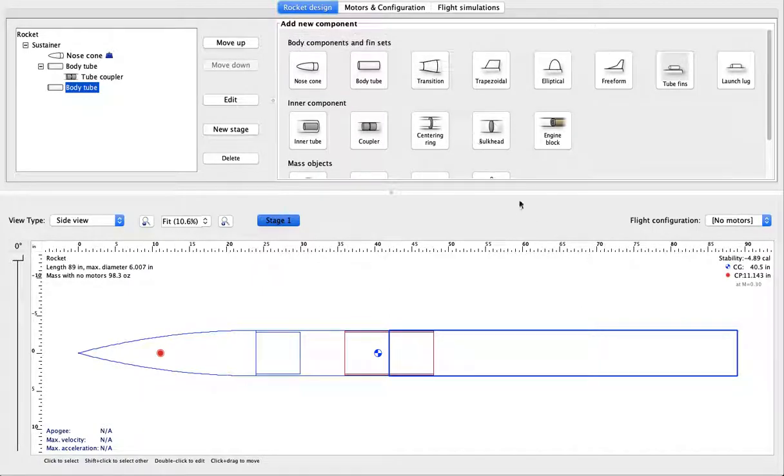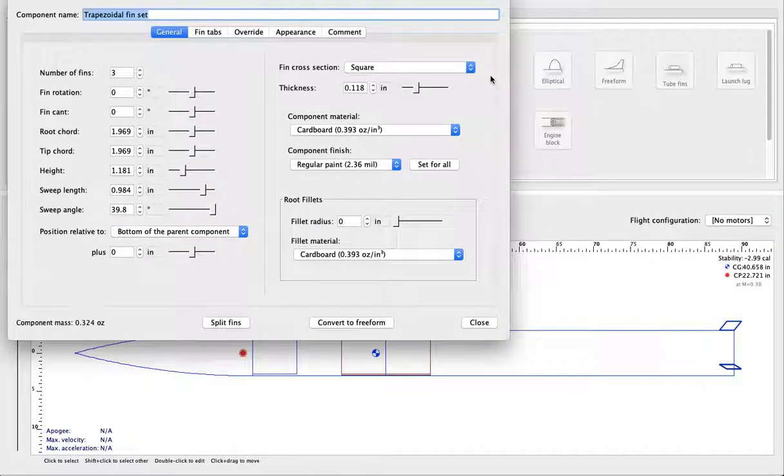So next up is our fins. The fins is where you can really play with the entire thing, play with your stabilities, and let's just hop right into it. So I like the trapezoidal. Freeform, you have a lot of authority. There's all sorts of science to these fins. Basically, you don't want them too big so that you would have so much drag, but you don't want them so small as to give up control. You don't want little nubs like this. That would be terrible. This would be a terrible flight.